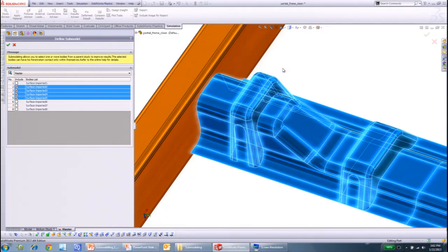When I say merged, if you take two faces that are touching and you do a compatible mesh bonding, it will try to align all the mesh from both faces where they're touching, and it'll merge all the nodes. So you have only one node because it's a common area. We can't do a cut for submodeling on that.